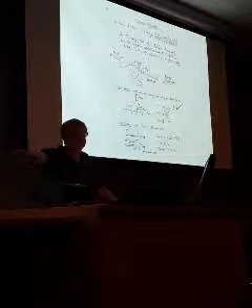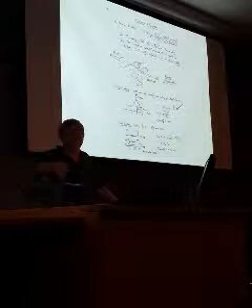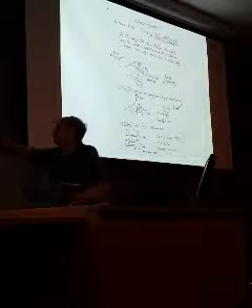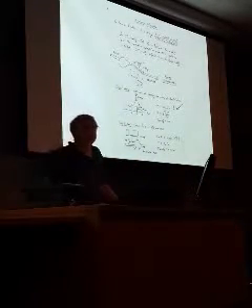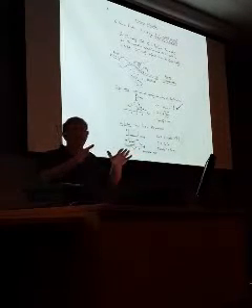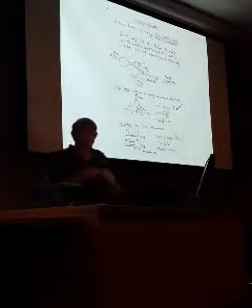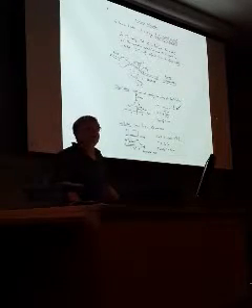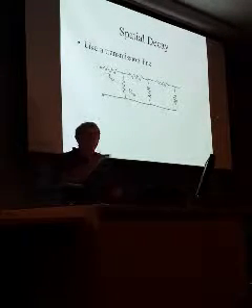All right? Capacitors are open circuits at DC. They go away. You don't even have to have a capacitor. This is a DC test. No capacitor. RL? That's not an RL. RL is a second order. If I have an RL, I get something that looks like this, some kind of response like that. So the only thing that I know of that produces this is a transmission line.